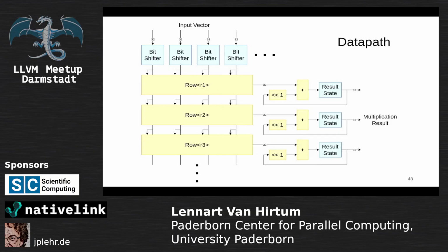Then, in effect, and certainly if this n is a constant, the implementation for this is in effect just wires. If your constant is, say, 25, and you're multiplying it by 1 or 0, then you would just be building the wires that say, okay, the bit is just wired to the 1 bits of this 25 constant. Am I making sense? Okay, good.